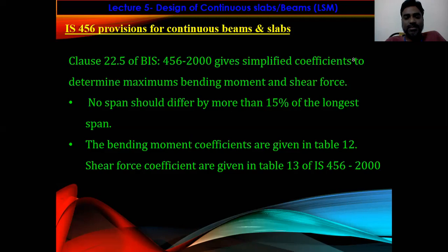So as per IS 456, there are some limitations for application of these coefficients. What are those limitations? You can determine the shear forces and bending moment based upon other methods also, like moment distribution method, Kani's method, or the stiffness method.